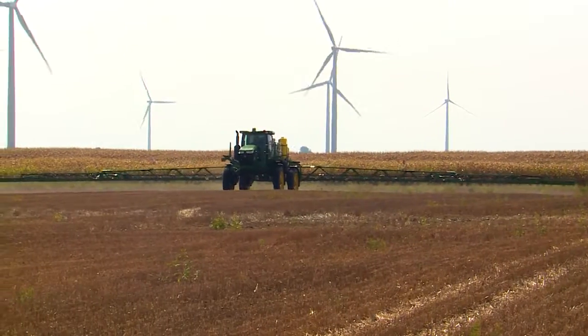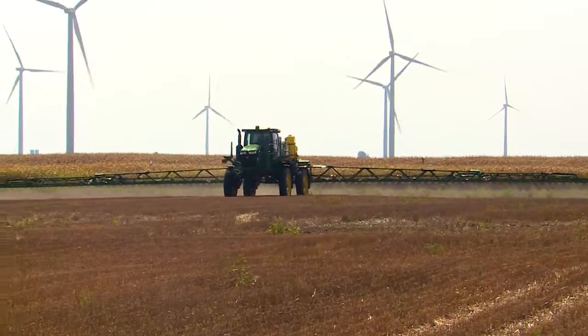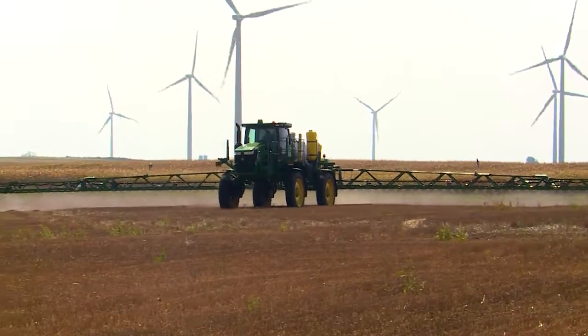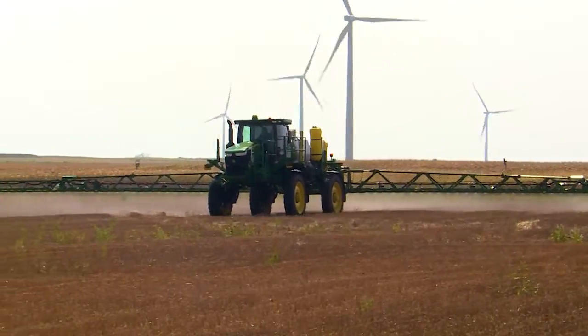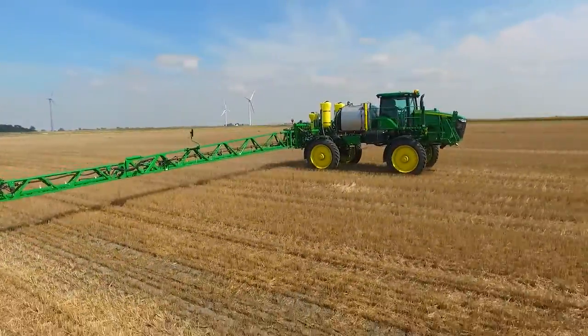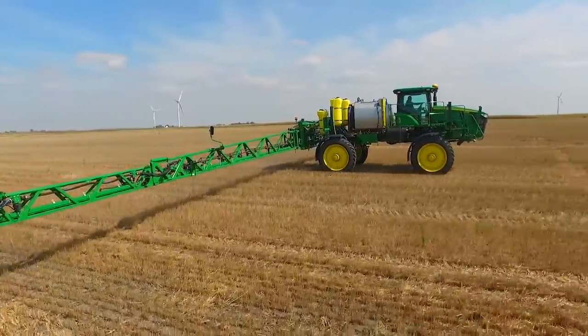Another concept that's very important to understand is what happens as you change speeds during the application if you're using a flow control system. As I mentioned earlier, most of the time the speed you operate the sprayer at during the application is based on the type of sprayer you're using, the terrain, and the location. How fast can you go while you're making that application? As you vary speed though, if you don't change any of the other variables, you also change your gallons per acre.